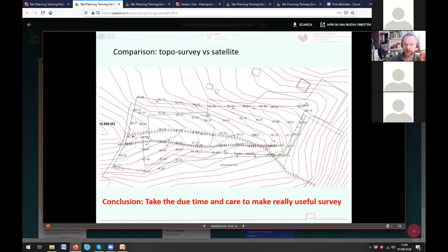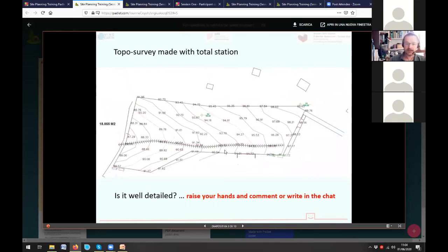Sorry, I have two answers. The first one is that when I designed this one, I was based on the interpretation that I was making of this contour line. Over here, you see that there is a turn. All the contour lines are turning. So I was assuming this is the slope going down, and that this could be the best place to lay the outflow stream of the camp if needed, based on the contour lines. So basically, this is a sort of valley.